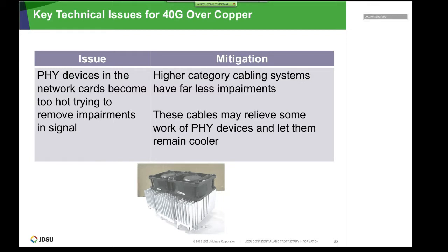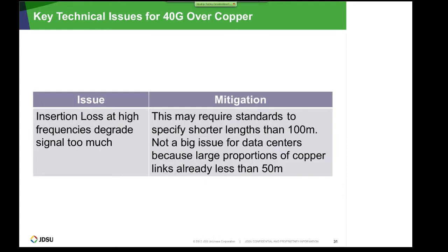The problem, as I already mentioned in the past, was that the devices had to generate very high output power. It means high output power created warming, and the devices had to have special cooling. If the request for output power is nowadays less than half, the request for cooling can also be reduced. It means the migration is to much simpler and cheaper transmitters, which generate much lower output power. Due to that, they will not require extra or additional cooling devices, like on this slide.